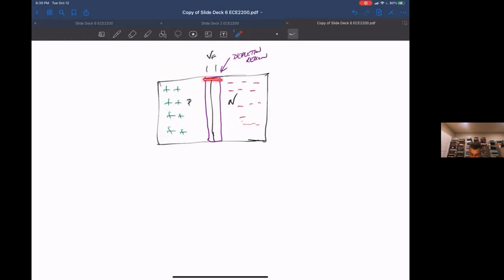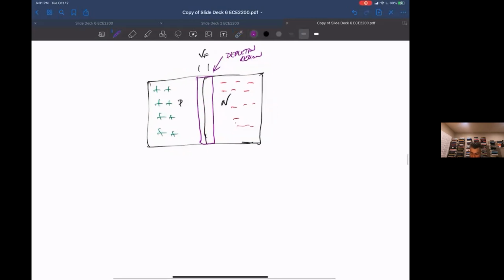So by reducing this electric field in the depletion region, we are allowing a diffusion current to flow. We have worked out the individual currents for the diffusion current, but we didn't talk about how the relative doping concentrations would affect it. It was sort of just implied, but let's look at the equation.